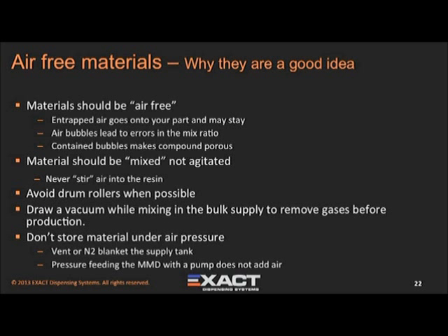It is very important to use air-free resins in your potting process. What does it mean to be air-free? It is simple in that you don't want bubbles in either the resins as you try to meter them in an accurate ratio, or have air entrapped in your cured part. It is critical to take steps to not introduce air into the resin with such things as drum rollers, and also to take the air out of the resins before you use them by a degassing process.